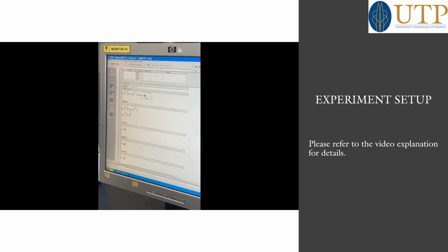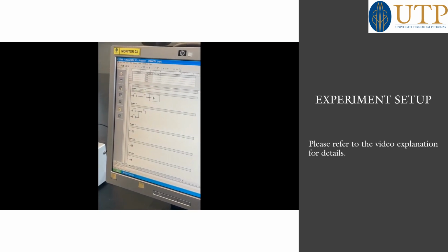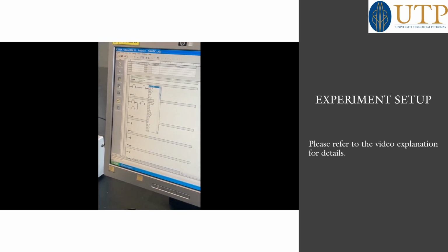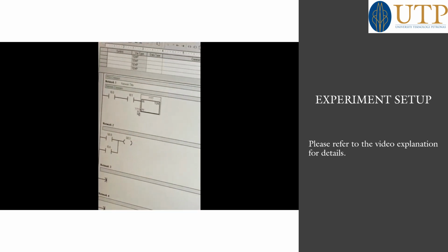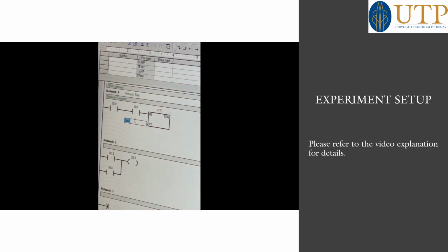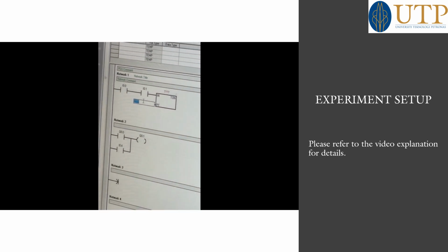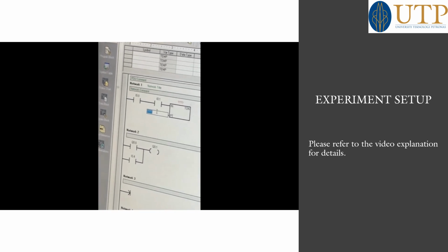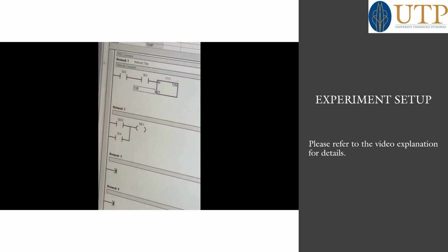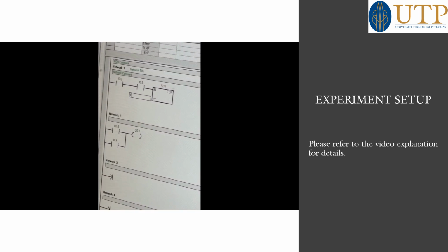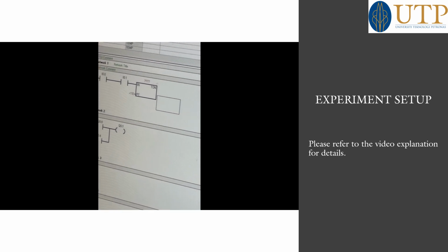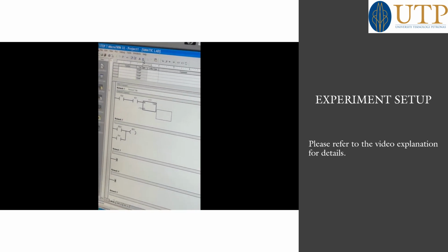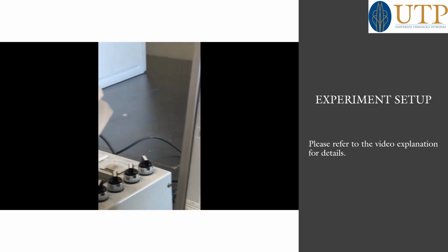And the third case, if you check, I'll just show how to keep this timer on delay. For that, just click here, click delete, and you click on the third icon here and drop down. You can see there is a TON button, timer on. Okay, for here we need to give certain values. Suppose you want to activate something after 10 seconds, then you need to give 100 here. If you want to activate something after 15 seconds, then you need to give 150. And then again you can repeat the same process, download, and you can start the input. So that is how you need to activate the timer on delay.